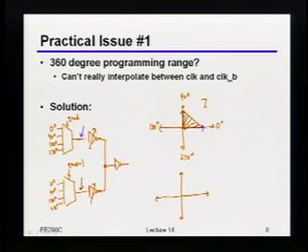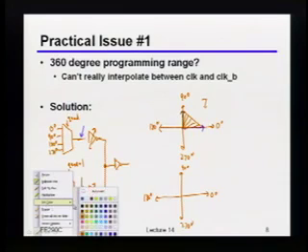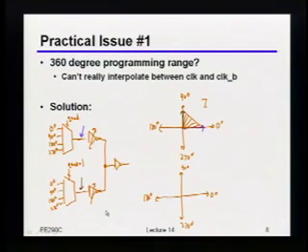Similarly, if I wanted it to be in the second quadrant, so it's again 0, 90, 180, 270, okay? Now, where should the blue be if I want to be in the second quadrant? And blue, remember, is the thing I feed into the top phase interpolator. At 90. Sorry? At 90. Yeah, okay. That's, by the way, it turns out there's actually two solutions, but indeed, this is one of them. You put it at 90. Okay? So if I do that, where's the other one? 180. Exactly, it's 180. Okay, so now, and of course, if you do that, then indeed, you will interpolate basically that way.